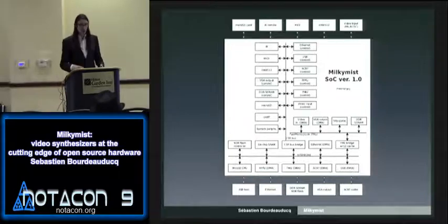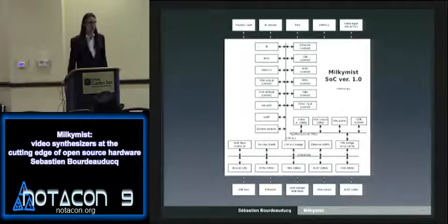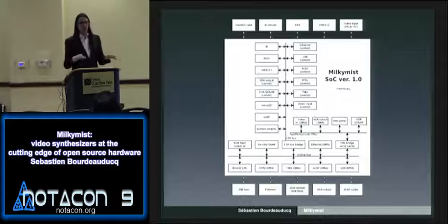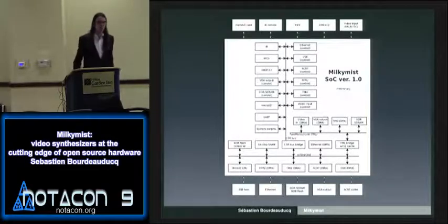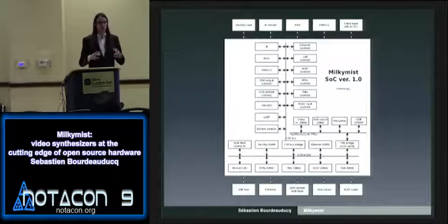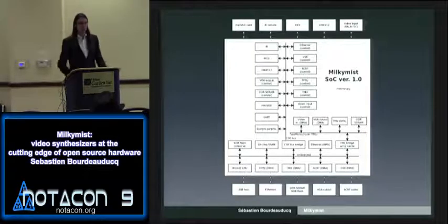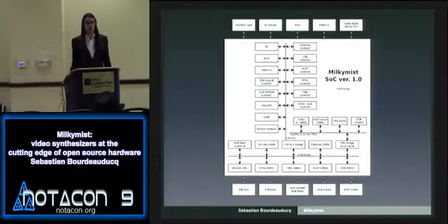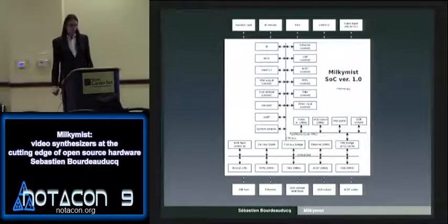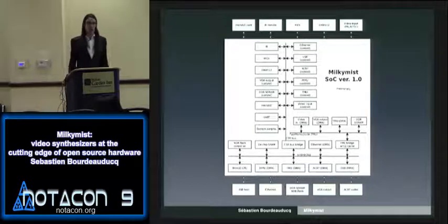When you have a computer like that, you have the CPU as a discrete chip made by Intel, typically, still these days, unfortunately, because x86 is not the best instruction set in the world. And you have a PCI bus and then peripherals, which these days tend to be grouped into Northbridge and Southbridge chips. But still, they are more like discrete chips. A system on chip is everything in one chip. That's basically what is used in embedded devices like iPads, iPhones, everything I mentioned. So one of the goals of this Milkymist project was to develop such a system on chip using open source design techniques.